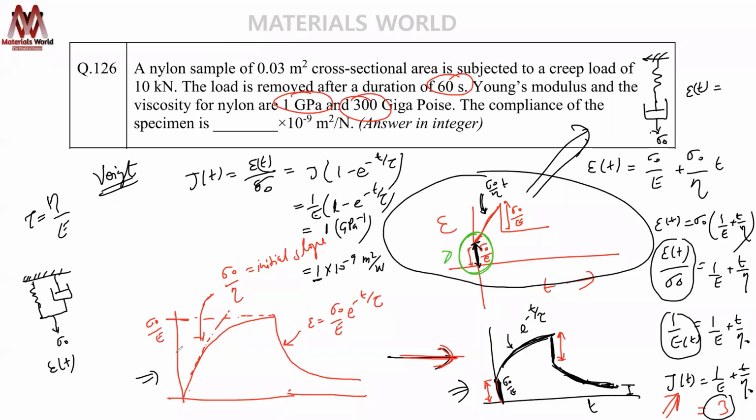Here we don't have any elastic deformation and recovery, but we need it in actual polymer. So here we can combine these two, and we can get a very accurate estimation of creep. I mean, it's an explanation of creep behavior of polymer. So what they have done is they have developed a 4-parameter model. Like you take Maxwell as well as what? Voigt.